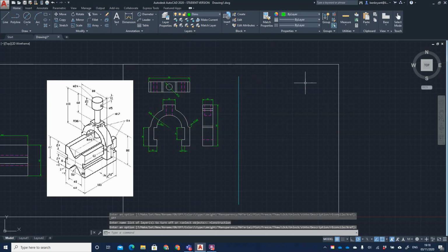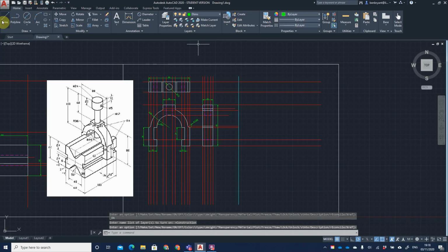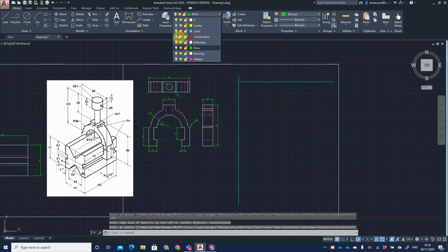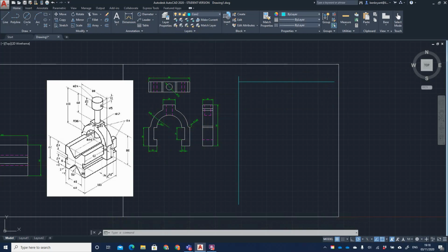So you're not having interfering construction lines. What I'm going to do, whilst I'm in here, is map that line across so I don't have to replicate it twice. I'm just going to turn that layer off. So the screw which sits in here is 100 mil tall.